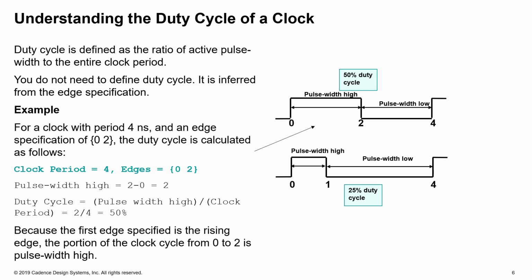That is important because in the case of a latch, when the latch is transparent or when the latch is opaque is determined by the duty cycle. It's also important what kind of flop is receiving the data. So a duty cycle can determine when the transfer of data is happening. In certain cases, duty cycle helps you, but in most designs, where there are either just positive edge triggered flops, or just negative edge triggered flops, or just latches, the duty cycle doesn't play much of a role.